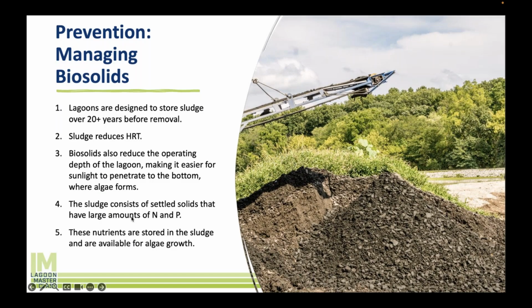So biosolids. This is, I would say, the most common reason that lagoons have, quote unquote, too much algae. And what I mean by too much algae is you are not meeting your pH, your TSS, or your BOD permit, right? You're struggling to meet that. Typically, lagoons are designed with 20 years of sludge storage, and typically nobody has ever removed sludge since the lagoon was first built.